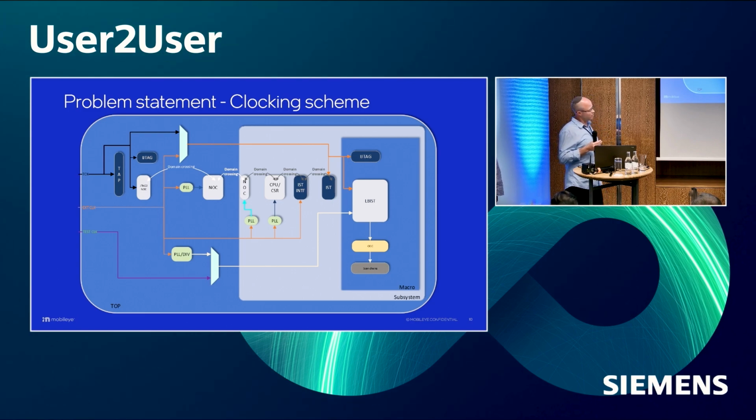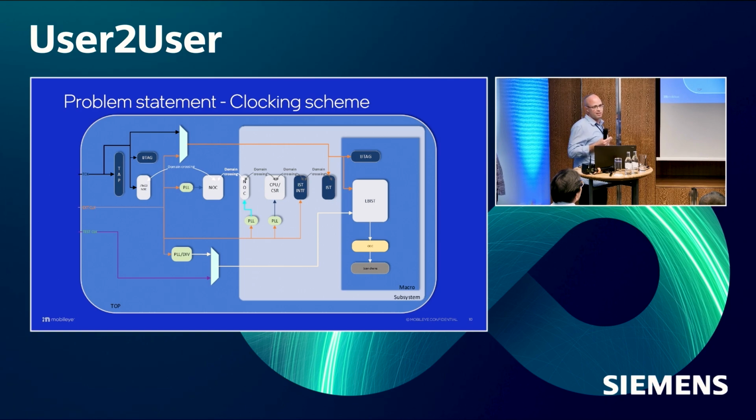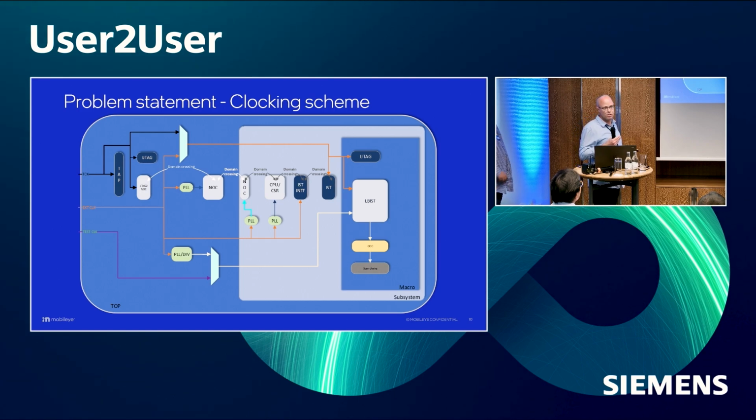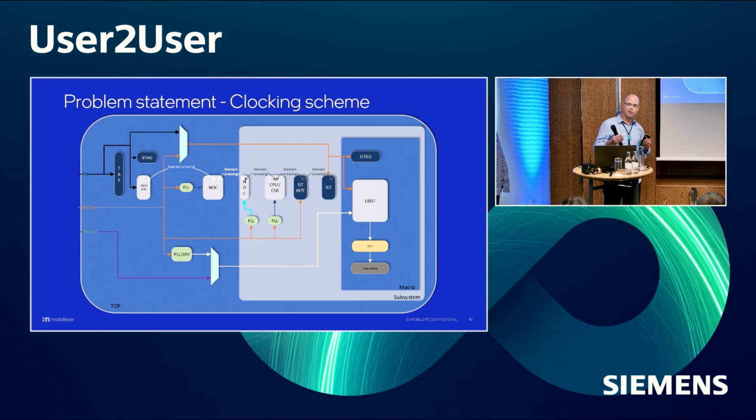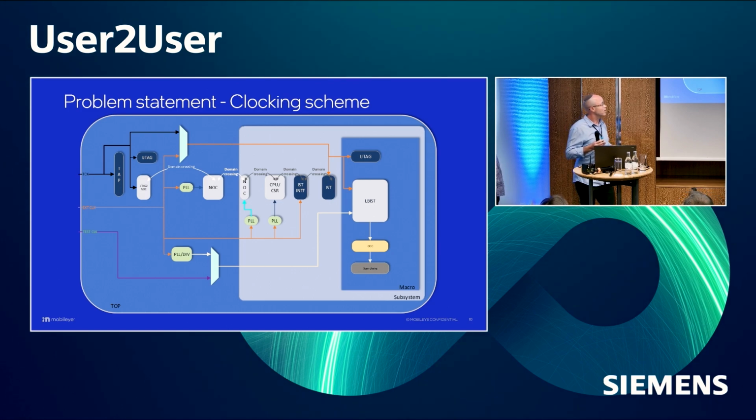It's already crossing the boundaries into your functional world, and eventually you're running the mission mode under your functional scenario with your real clocking schemes, synchronizations, your custom logic, and Tessent can't cover that for you. This is why it's important. If you intend to use mission mode logic, you need to remember that mission mode is already crossing the boundaries to your functional logic, to your functional scenario. And it's up to you to actually cover that during production. Otherwise, you might have faults in your design which are not covered during production.